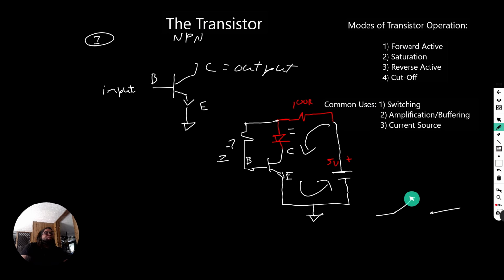So let's say, for instance, you'd say, well, what's the point of that? Well, let's say we wanted to make this LED flash, right? An LED flashing circuit has been a very popular circuit since electronics came out. There's multiple ways of doing it. One way to do it like this is if we had, let's say, a 555 timer.